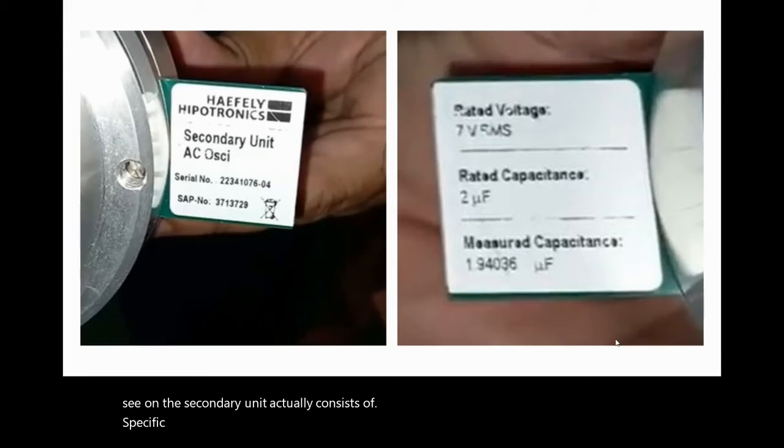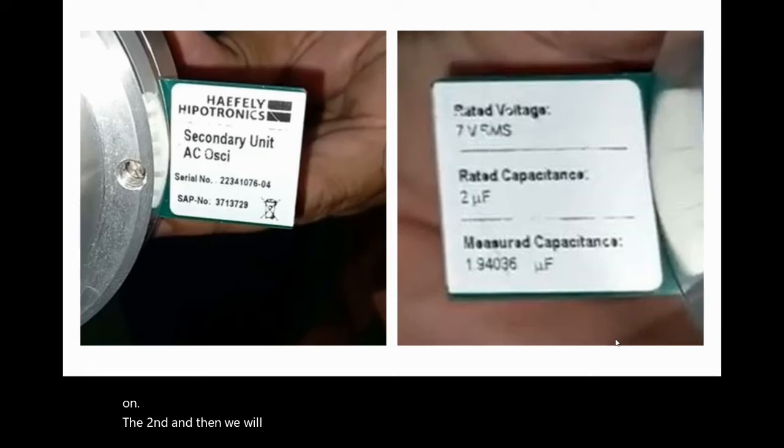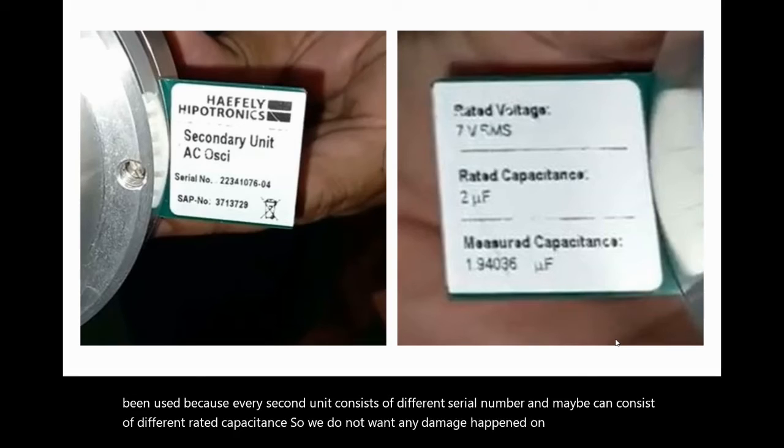capacitance rating. So here, as you can see, based on Dr. Zikri, we have made sure of the serial number first and made a note of the rated voltage for the secondary unit, also the rated capacitance on the secondary unit. Then we will note the measured capacitance to make sure which secondary unit we have been using, because every secondary unit has a different serial number and maybe a different rated capacitance. So we do not want any damage to happen to our equipment, so we must make sure of that first.